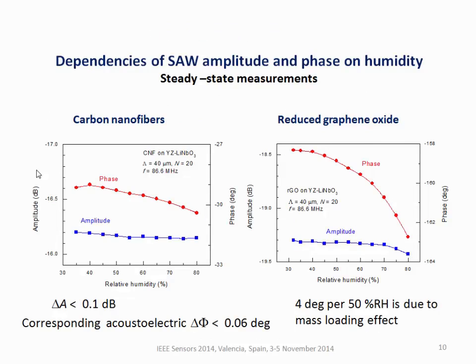So as I started to speak about humidity sensors, we investigated the change of surface acoustic wave amplitude and phase on humidity. Very briefly, amplitude was almost constant and phase change was more pronounced. This allows us to conclude that it is the mass loading effect which is responsible for the observed phase changes.